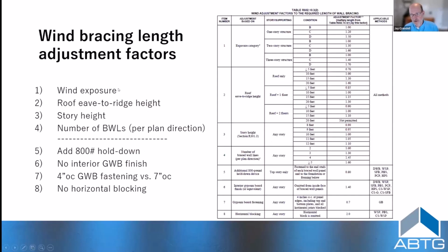They address wind exposure, which has a huge effect on your bracing amounts, up to 50%. The bracing provisions are actually based on sort of exposure B, which is the more conservative kind of protected condition. But that's where probably 70 to 80% of homes land, in the middle of a development or in a mix of trees and development. But if you're in a more severe open exposure or a waterfront type of exposure, then there's going to be some increase in bracing.